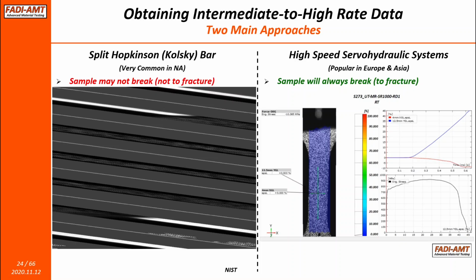Next comparison is a problem that is known with the Kolsky bar. Again, when we talk about deformation by this pressure wave that's generated, this wave has a certain length and duration. And in most cases, if you're dealing with a highly ductile material or even just decently ductile material like a mild steel, your wave will likely sort of fade away before you finish the test.